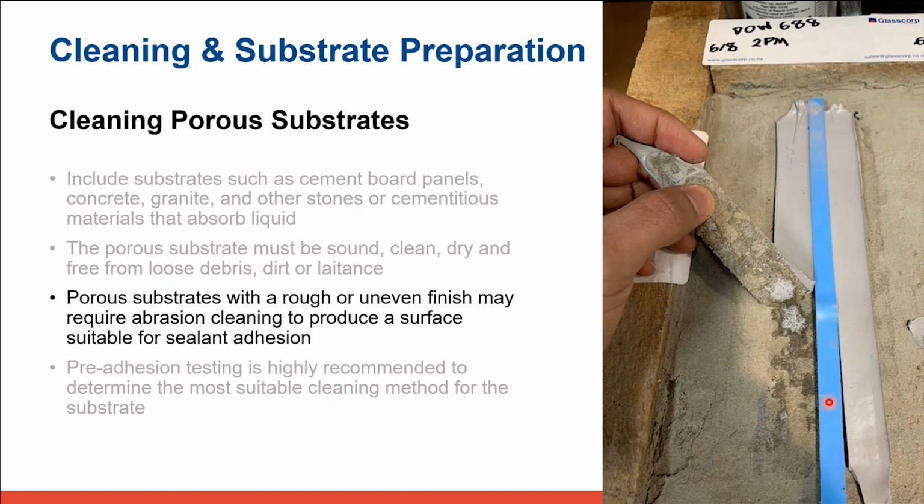So in this photo, we've got obviously another concrete sample that was provided for testing with a very different quality of surface finish. So the surface on the sample was quite loose and dusty, so I found a cleaning solvent wasn't practical to use here. And I've tried to sort of dust the surface and remove any loose material. Even after adhesion testing, you could see the sealant stuck to the top sealing face, but that layer peeled straight off the substrate. So not a great result.